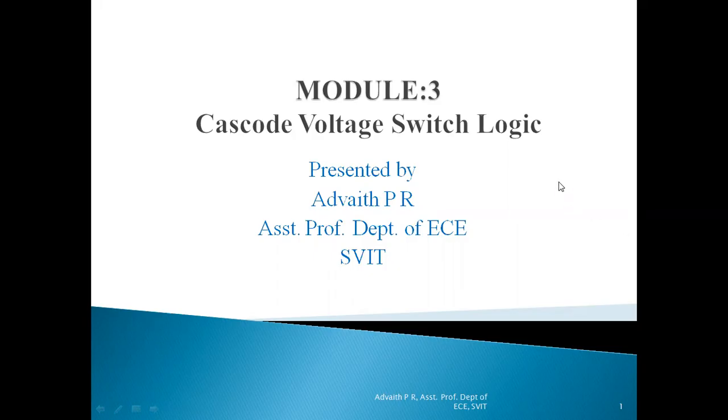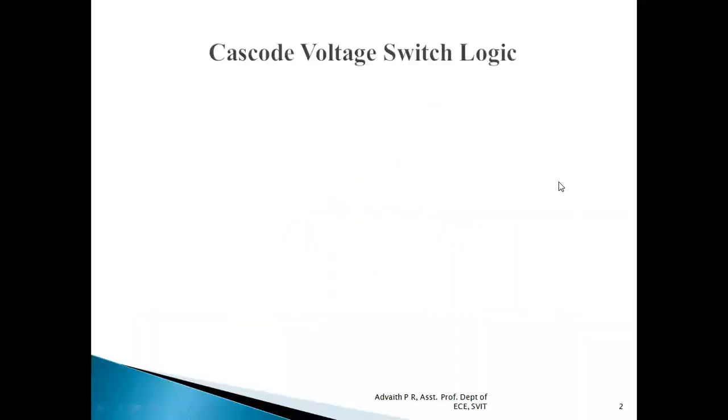I'll be discussing cascode voltage switch logic. Cascode voltage switch logic seeks the performance of ratioed circuits without the static power consumption. It is normally called CVSL, cascode voltage switch logic.